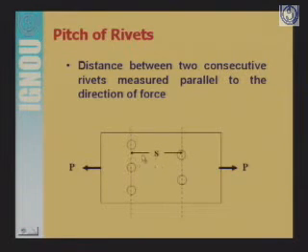So here, as you see, this distance parallel to this force P is shown here as S. So this distance between two consecutive rivets, in the direction parallel to the direction of the force, is S, and this is called the pitch of the rivets.